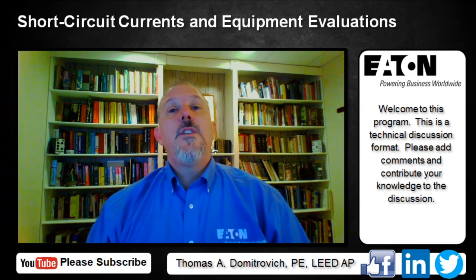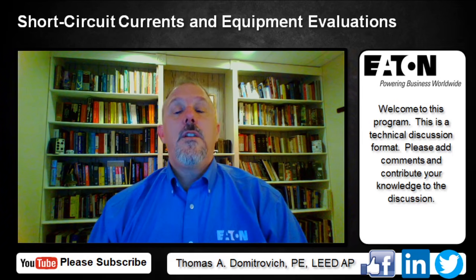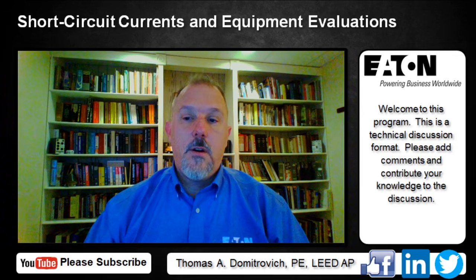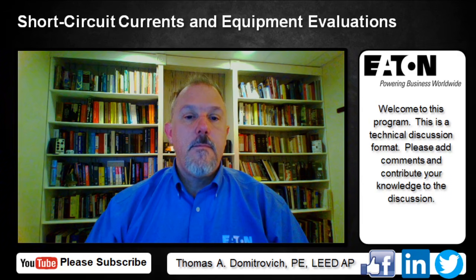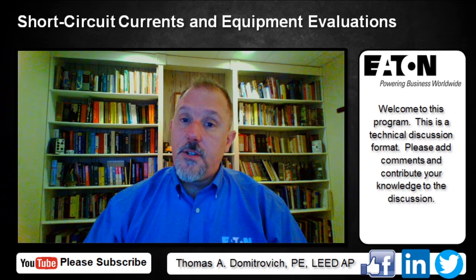Dan Neeser says the 2 to 1 ratio is not for all fuses. You have to go by the ratio tables that are in the published manufacturer's information.